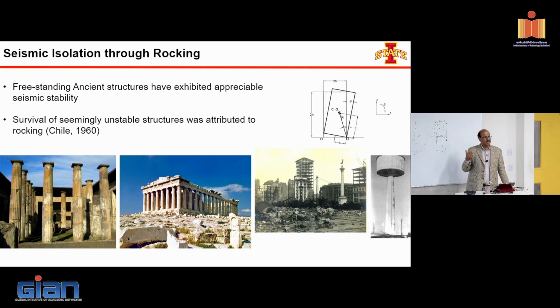So remember we said single rocking wall, if the damping is less, you can increase the design force. If the design force has a small increase, that is one thing, but if it's increased by 50%, people then say it's going to add cost to it.